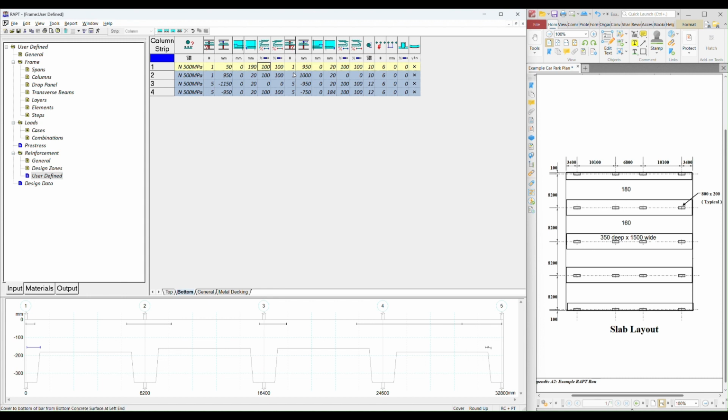And we'll bring it in, let's say 1200. We know that we can't get 100% development, so we'll put in 50% because we can cog it on the left hand side, and we add 0 here because we will just have standard development length. Let's put in N12s, and we will have them spaced at 300 because we know that's the minimum spacing.